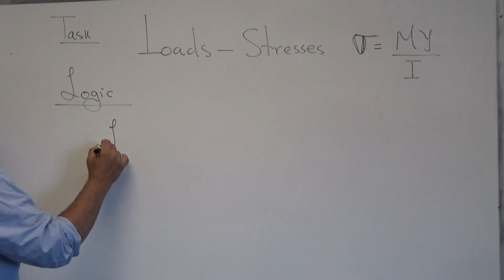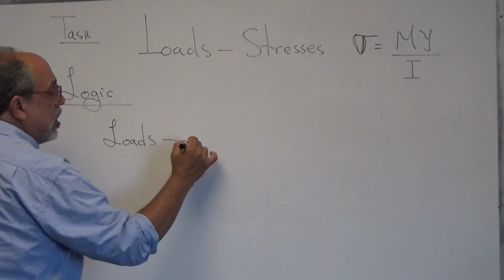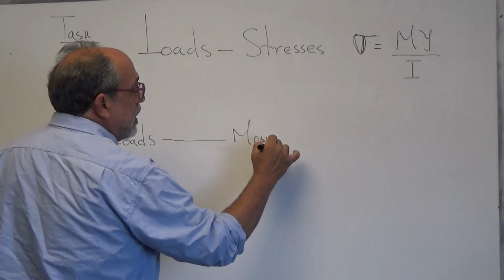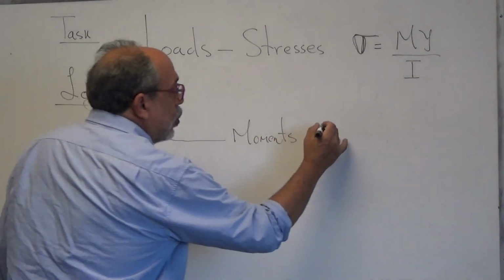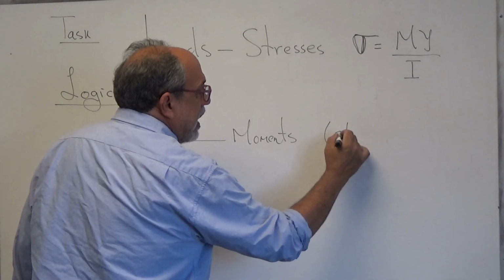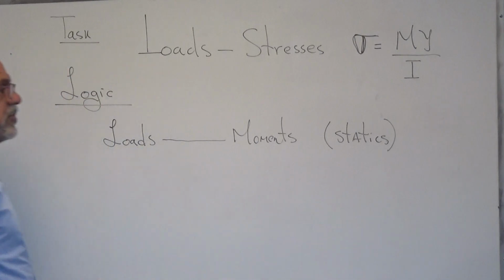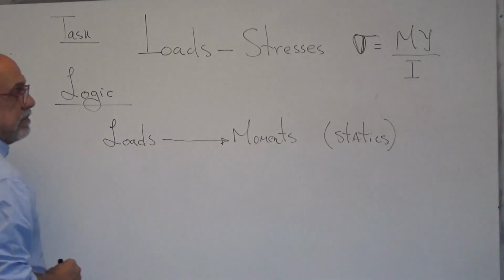We will have loads, and from those loads we're going to find moments, which are actually stress resultants. And the tool that we're going to use is statics, right? Because that's all we know right now. All our structures are statically determinate. So from loads we will get moments.